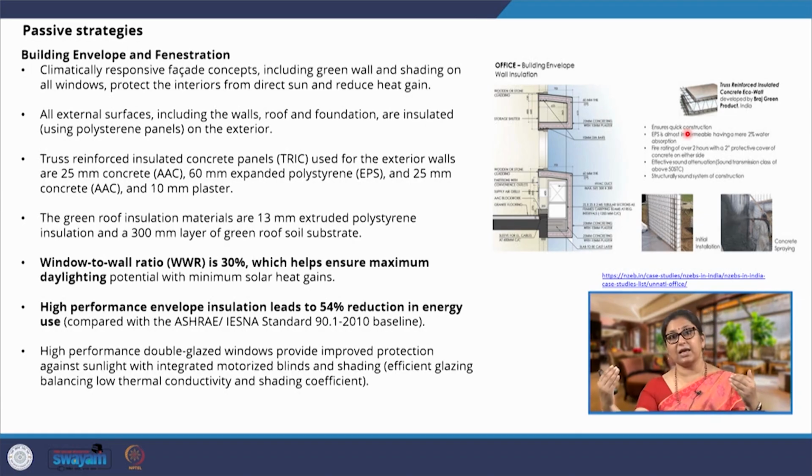So, the surface area has been increased by providing a courtyard, and of that surface area 30% of the wall surface is window, and that is sufficient to daylight all the habitable office areas.